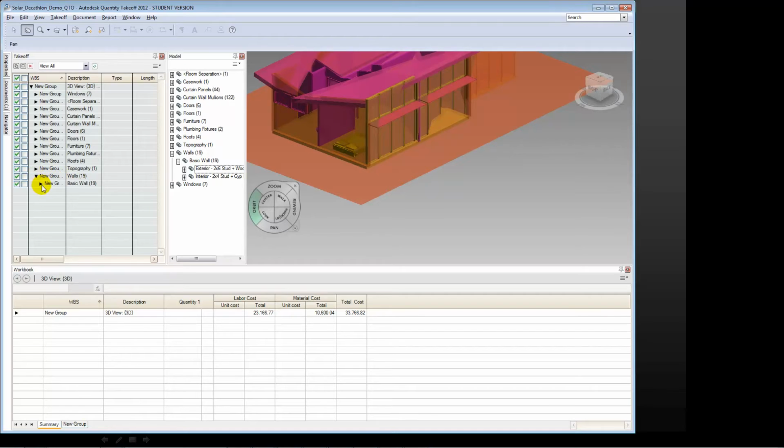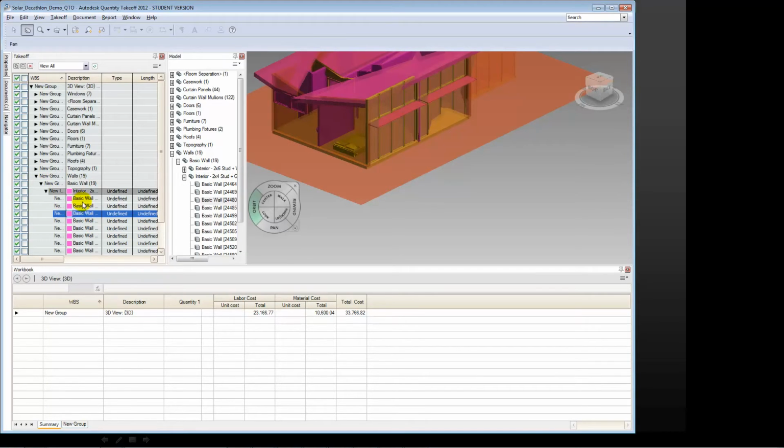For example, for all the different walls in the model, based on the different types, it's itemized them all. So all the different walls, and within each of those different walls, the area, the size, the length, all those different things are available to us. So you have a quantity takeoff that's accurate to the model quantities. You never really have to worry about making a transcription error. If it's in the model, the quantity will be there. If you update the model, the quantity will update itself also.